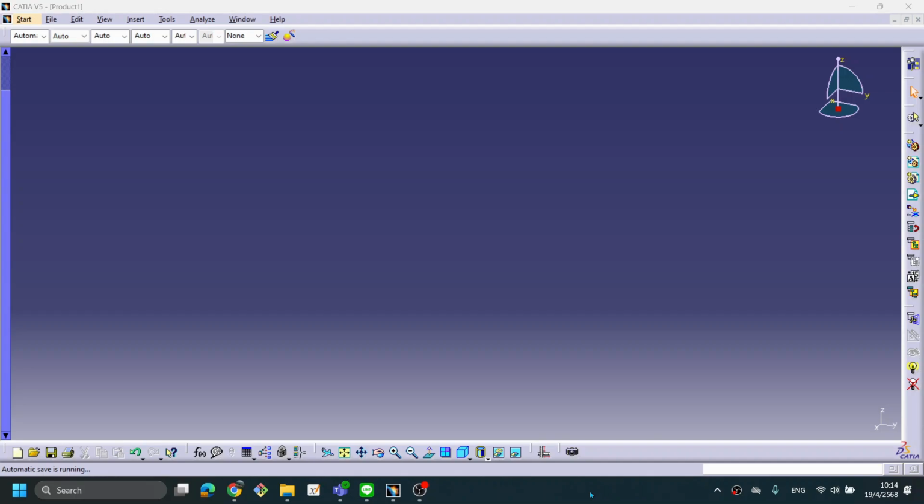I will be teaching you how to set up the mini CNC, the real mini CNC, and correlate it with the G code generated by CATIA, right? And set up the tools. Then use the G code, upload it to the CNC, and control the axes of the mini CNC. The three axis mini CNC moves to the part and cuts, going along with the G code you generated before.